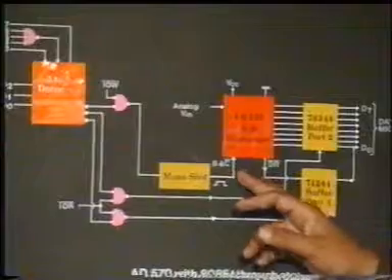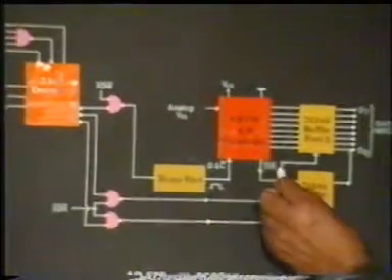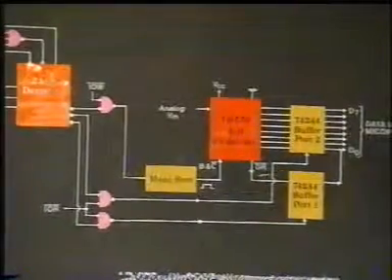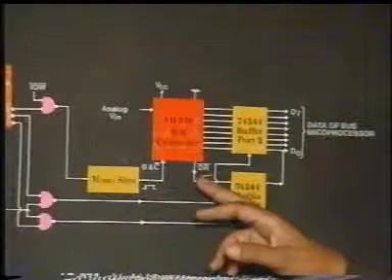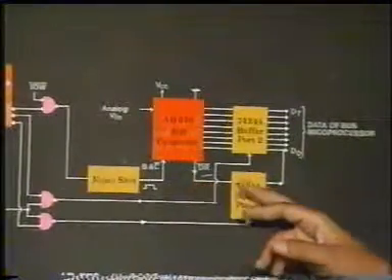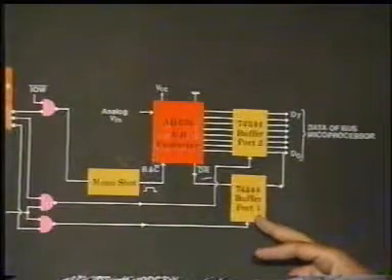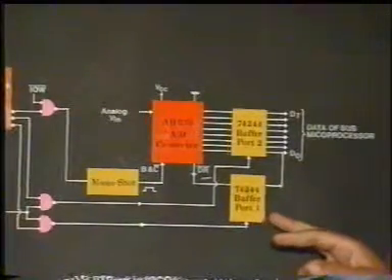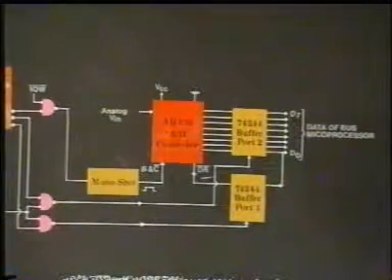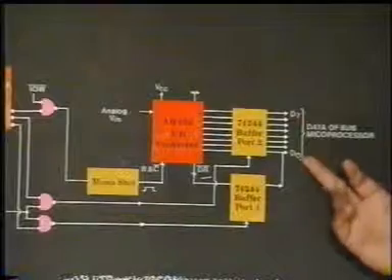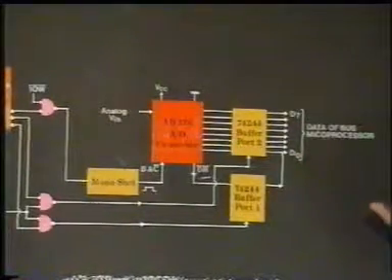As soon as BC bar of sufficient pulse width is made available to this, DR bar signal, that is data ready bar signal, is deactivated. This goes deactivated high, and the microprocessor checks the status of this line through a port, say port 1. Now this is connected to D0. What does the microprocessor do? It says read port 1 and check for this. If it is high, it again continues reading this port and checking its status.